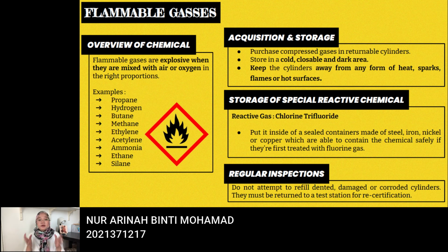fluorine gas. Regular inspection that should be taken is that if the cylinder is more than 10 years past its date, the cylinder cannot be refilled. Do not attempt to refill dented, damaged or corroded cylinders. They must be returned to a test station for recertification.